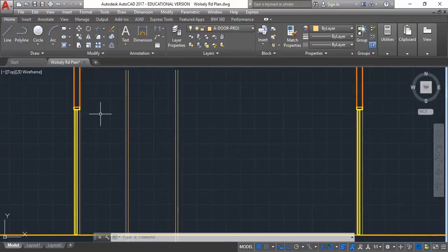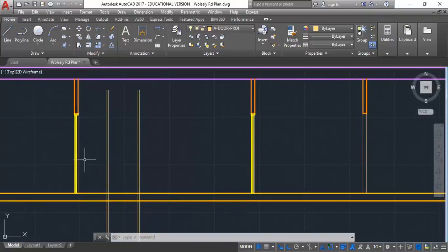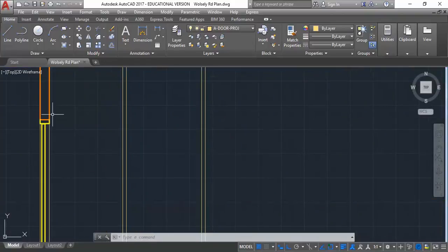And there's a common drawing method that a lot of designers use, which is plan, section, elevation. There's a reason they say it in that order. Because if you do the plan and then the section, you usually have all the information you need to draw the elevation. So there is a reason.